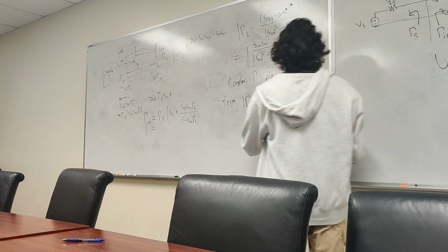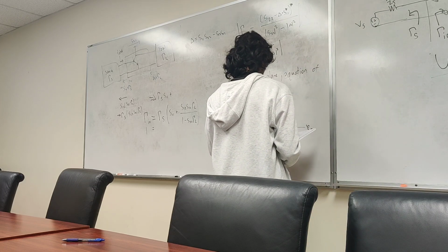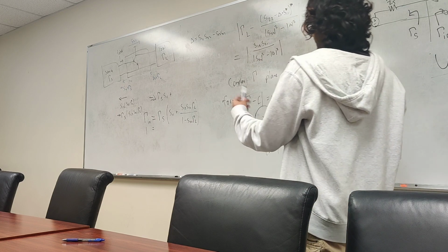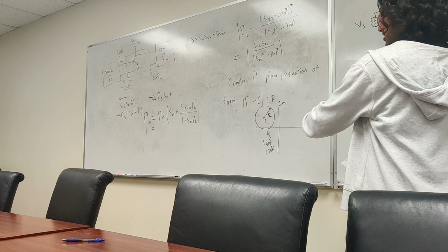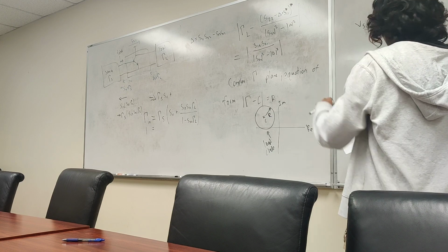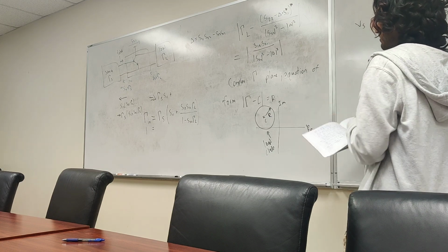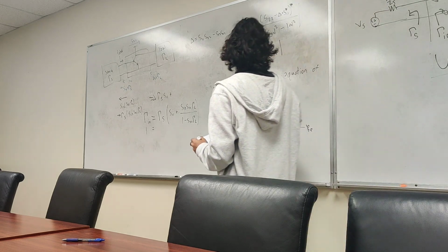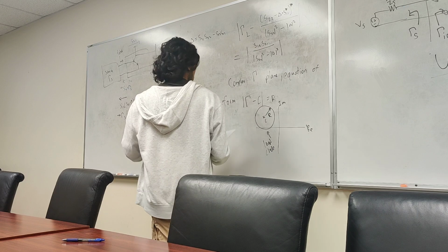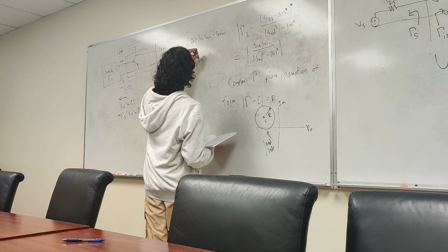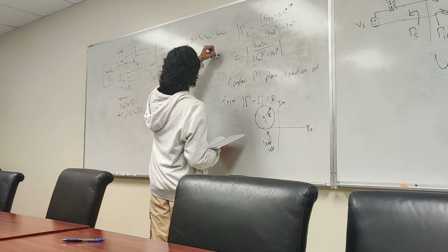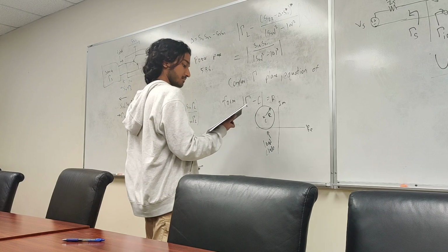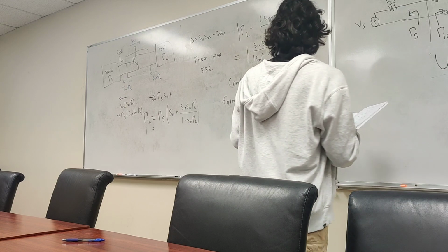And we call this a load circle here, because we're saying gamma in equals 0, and if we say gamma out equals 0, then we have a source circle, at another point C with a radius r. Different C, different r probably, but the same concept applies. If you want to see an example of this, there's a page in Pozar, page 586. If I have time, I'll show it to you guys, but if we don't, then you can look at that.